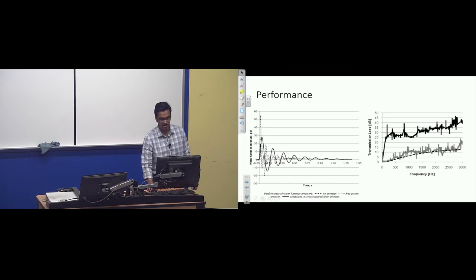And free piston-based are still a lot better. So you can see it's almost like 5 or 10 psi. Their performance in terms of the reduction of peak pressures was still observed to be much better than the compliance-based water hammer arresters. But it's a continuous improvement, and what we're trying to do is identify and make polymers, basically optimize the polymer, so that they can perform as well as the gas spring kind of arresters. And that's it. Any questions?